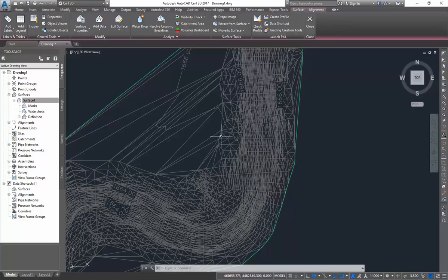So it just uses straight line interpolation between any of these known points, and so the shorter the sides to any of these triangles are, usually the better information or the more dense the survey points. But then you get locations like this where you have long straight lines between different survey points, and it's just using interpolation. So you could actually have a large outcropping along your river, but this is going to portray it as a relatively flat, or at least a constant slope.